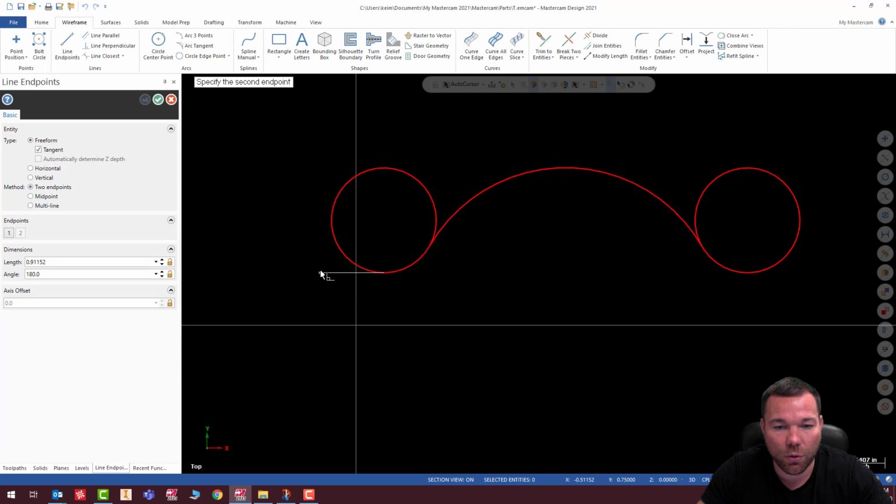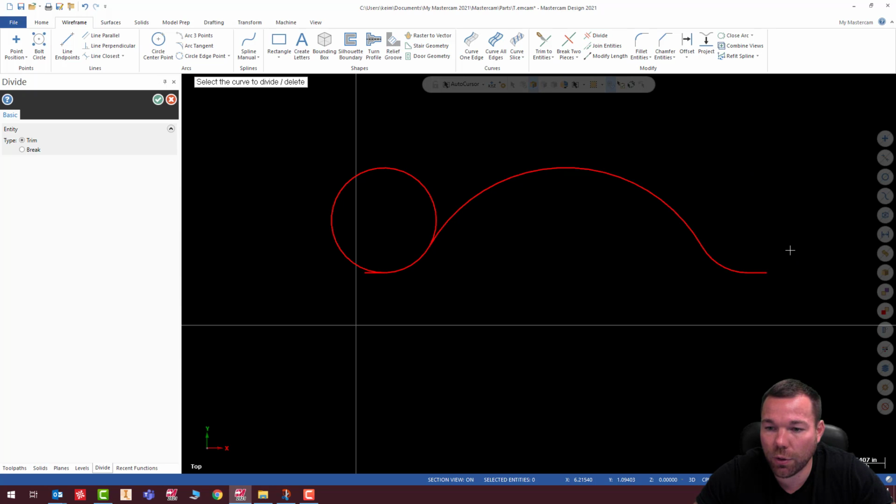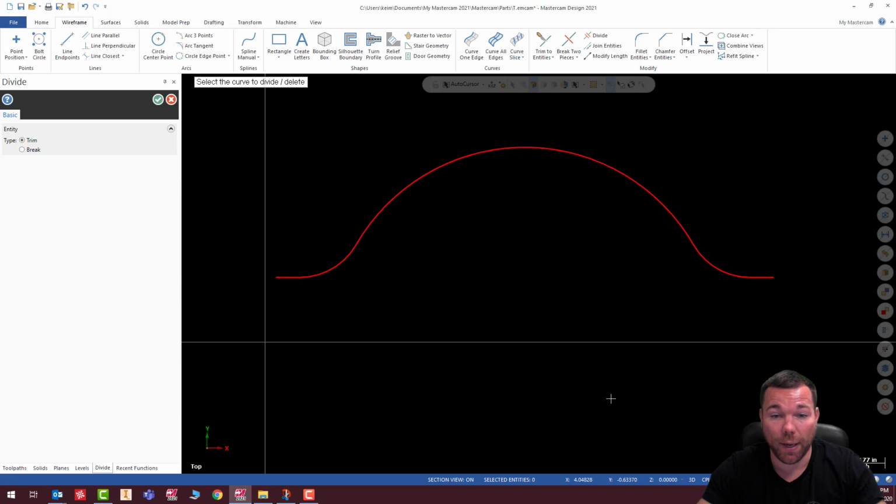The next thing I'm going to do is create a line here. And it looks like my endpoint is going to be 0.125, comma 0.75. Okay. And this one here, same thing. Looks like this one is 5.875, comma 0.75. Enter. All right. Then we're going to go back and trim these here. So, whoops. Didn't want to do that. Okay. And there we go. So there's our path. That was pretty quick and easy to create.